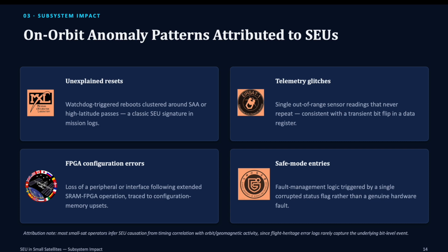On the ISS, there were two quad modular redundant FPGA payloads that flew for about 13 months, and one of them experienced a rare multi-core fault that was created from configuration memory SEUs, which the team then reproduced on the ground to see how it propagated.